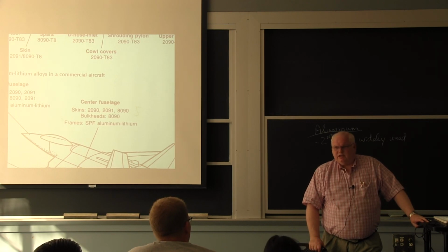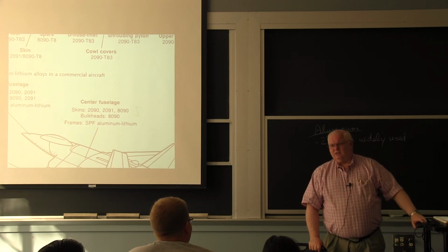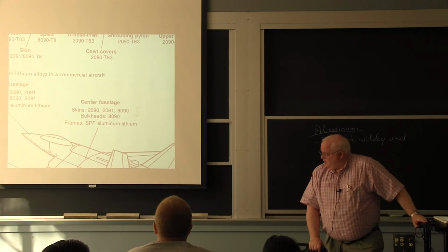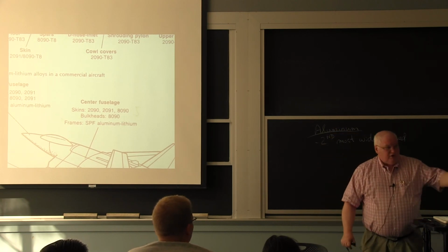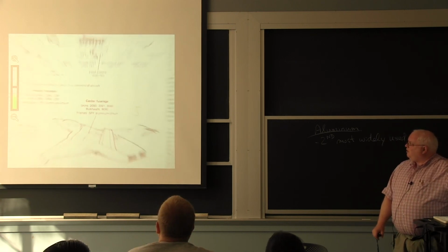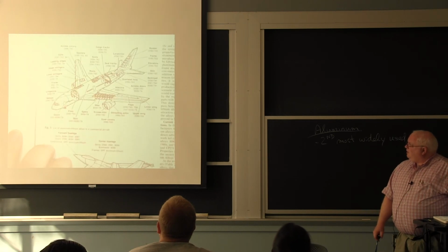In the 70s, they started getting better fatigue resistance. Lots of fatigue data. More fatigue data on aluminum than on steels. There's actually a reason for that I'm not going to go into. But one of the reasons is we use them for aircraft, and aircraft are nothing more than flying fatigue machines. They vibrate, and they tend to be life limiting.